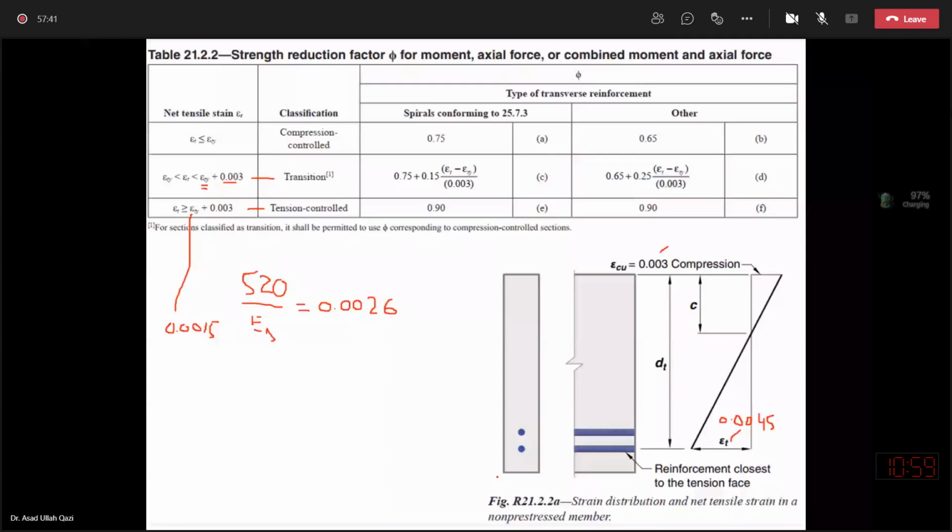But now in the latest working conditions, since higher grade steel bars are also in practice, to accommodate them, now they are suggesting to calculate their yield strains, then add them to 0.005, so that even for higher grades, we can also decide a safe magnitude of strain to ensure the ductility warning in the cross section. So this is a little amendment in the current publication.